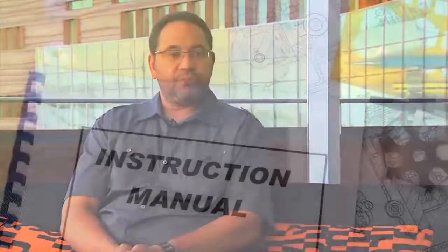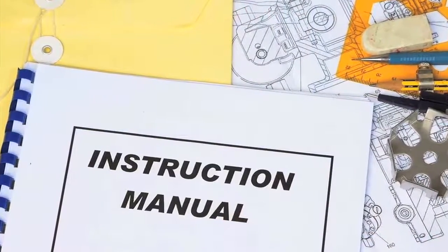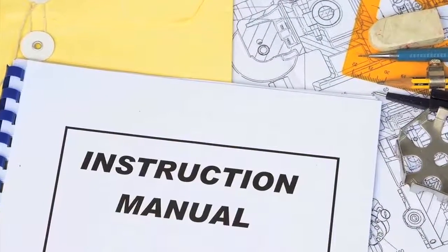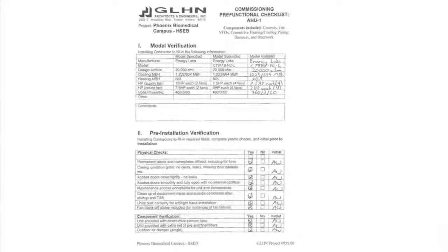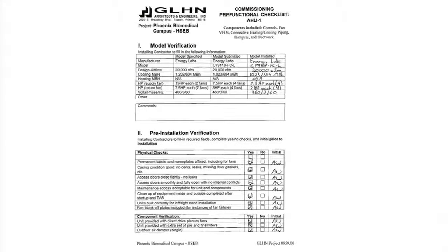commissioning effort, having manuals put in place to describe the commissioning efforts, producing your pre-functional checklists for the subcontractors to start their pre-functional checks, and then also providing the functional testing in addition to the verification and also ensuring owner training.